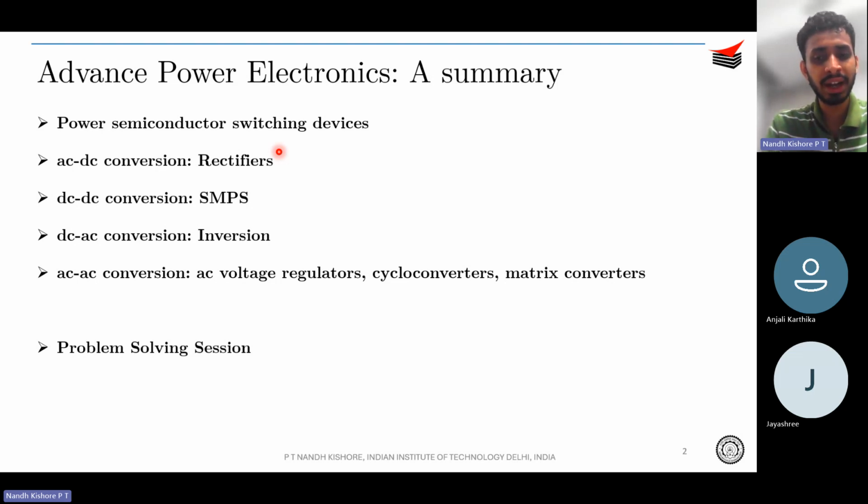After that, you also had a session in the last week on power quality issues. You went into passive and active filters, with categories such as series filters and shunt filters. Basically, filters are just LC elements tuned to a particular resonant frequency, so that they shunt out or remove the harmonic of that particular frequency. Your total current is now one harmonic order less, therefore your THD will obviously improve.